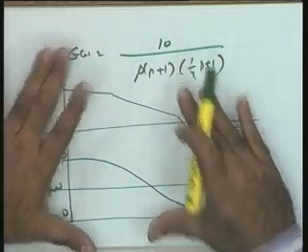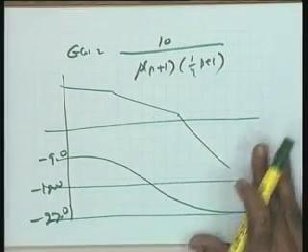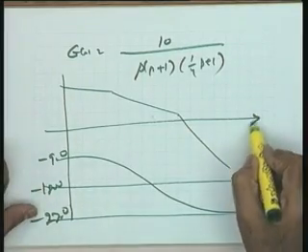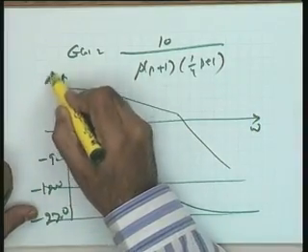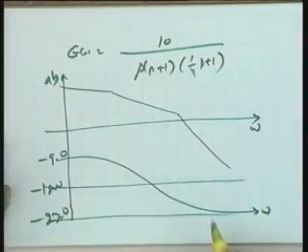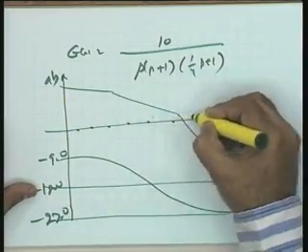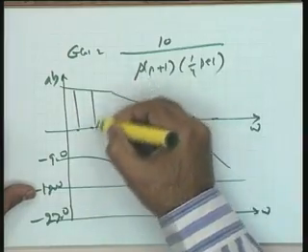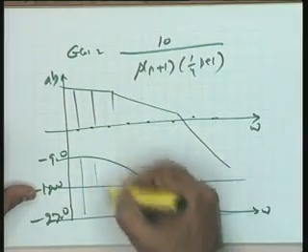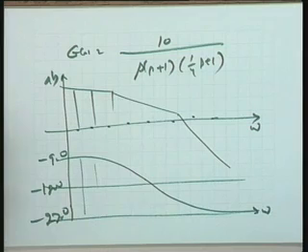So, with this magnitude and angle plot available to me, on this omega scale, omega versus dB and omega versus phase angle, what I do is I take some points on this axis and read off the magnitude and the corresponding phase angles at these omegas.